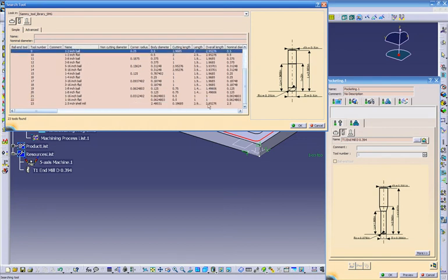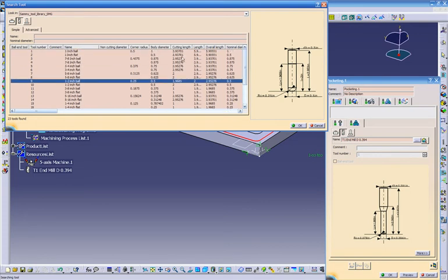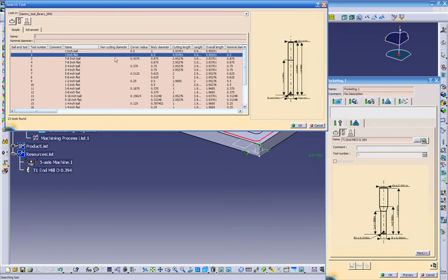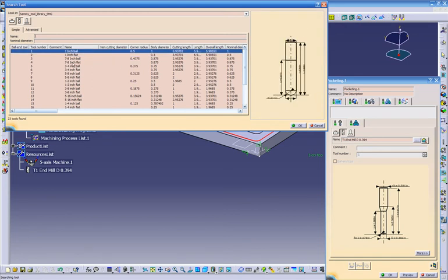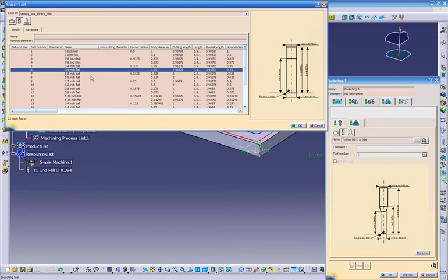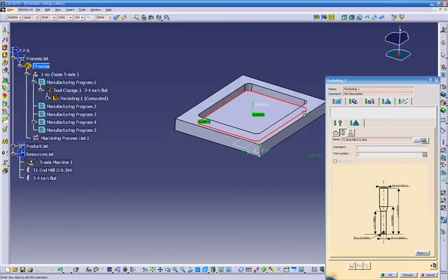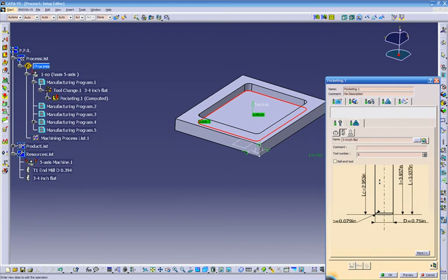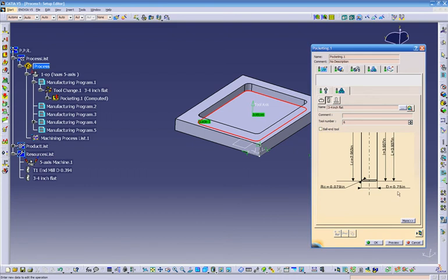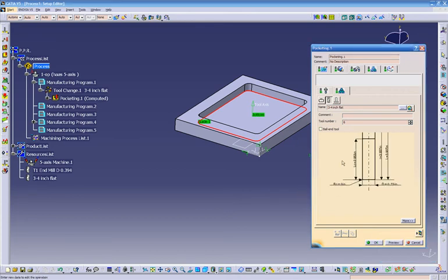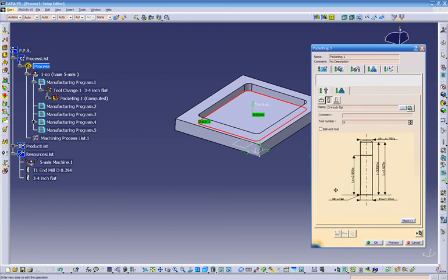This is standard diameters. And for example, let's say we want to choose a 1-inch flat. Let's click on 1-inch. 1-inch ball. 3/4 flat. Click OK. And you can customize it. Even my operation, even though I said it's a 750, for some reason it puts this radius in here, but you can double click on it and make it 0, make it a sharp corner.